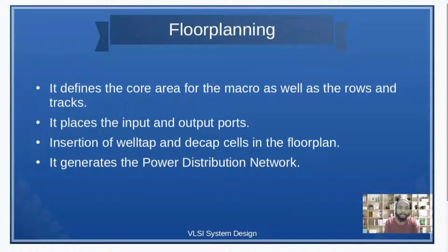Then we will proceed to the floor planning stage. Here, the core area and the macro area, as well as the rows and tracks, are defined, and the input and output pins are also placed in this part. It also involves the insertion of well tap and decap cells, and in this step only the power distribution network is generated.